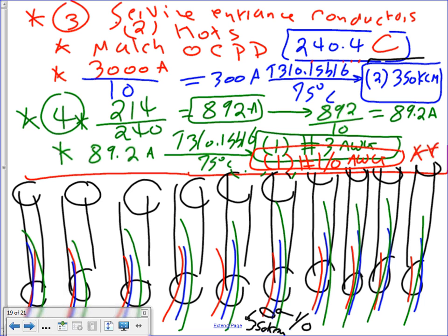So here's your 10 conduits. This is my conduit 1, 2, 3, 4, 5, 6, 7, 8, 9, 10. Each one of these conduits is carrying 2 conductors 350 kcmil, and 1 conductor 1/0. Can I have thumbs up, Chad? That's how they wire the apartments in downtown Minneapolis.